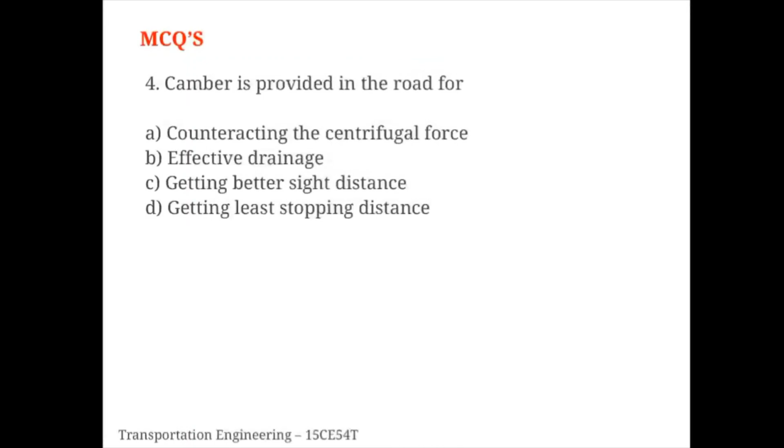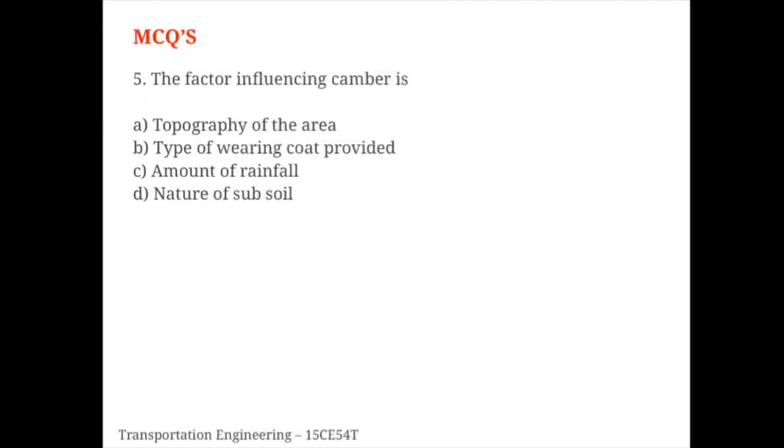Camber is provided in the road for effective drainage. The factor influencing camber is topography of the area, type of rainfall provided, amount of rainfall, nature of the subsoil.